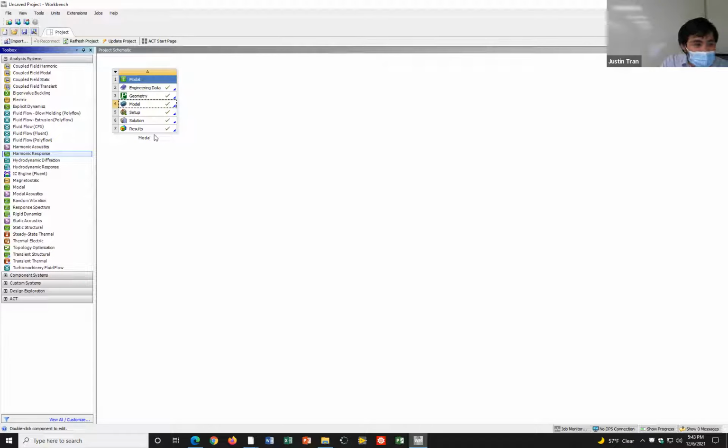And so I actually don't know if that bug still exists on here or if it was just my laptop being weird. But when you create this harmonic response, you're of course going to link it with the modal analysis, right? Because you can almost think of the harmonic response as the follow-up study after you do the modal analysis, okay?